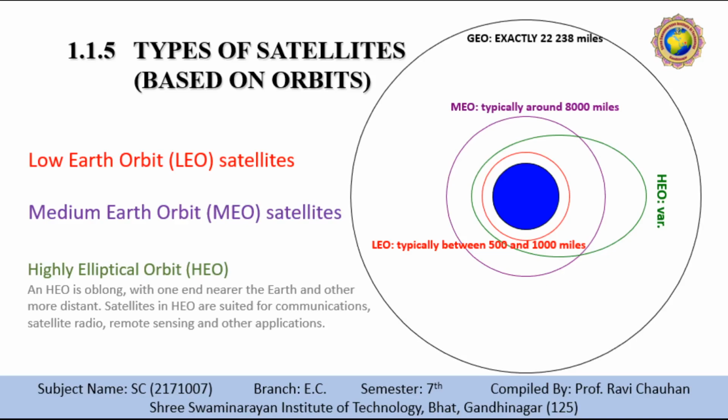Using orbits around 10,000 kilometers, a system only requires a dozen satellites, which is more than a GEO system but much less than a LEO system. These satellites move more slowly relative to the Earth's rotation, allowing a simpler system design. Satellite periods are about 6 hours. Depending on the inclination, the MEO can cover larger populations, so it requires fewer handovers.